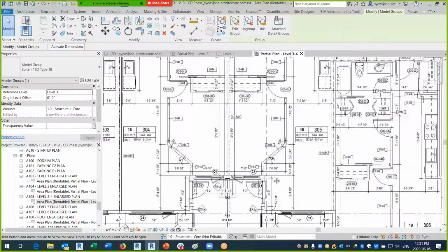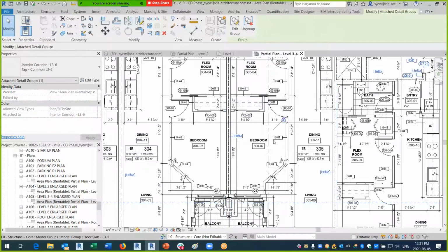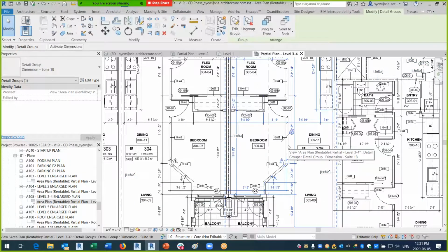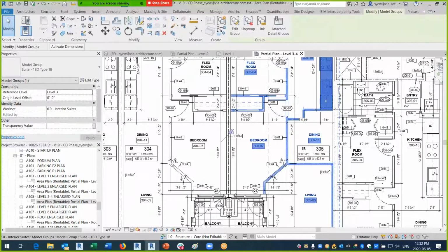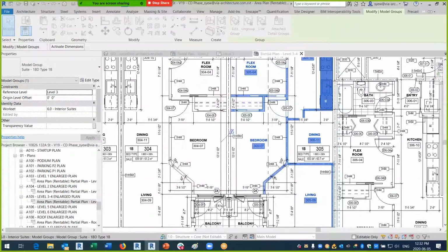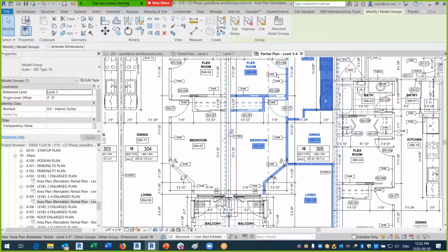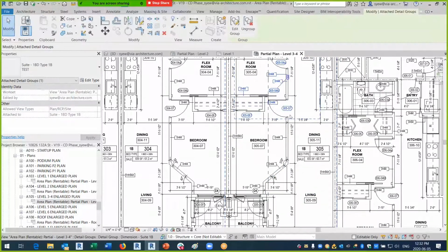So if you're doing mirror objects, let's assume that your tag is overlapping. You can actually swap it. Let's assume this is, not this one, sorry, this one. It's always selecting. There you go. You can always say, okay, swap it with this one. And there you go. So it basically creates that extra tag that's added to that. It's a very useful thing, especially when you're doing a lot of high-rise or repeated units and stuff like that.